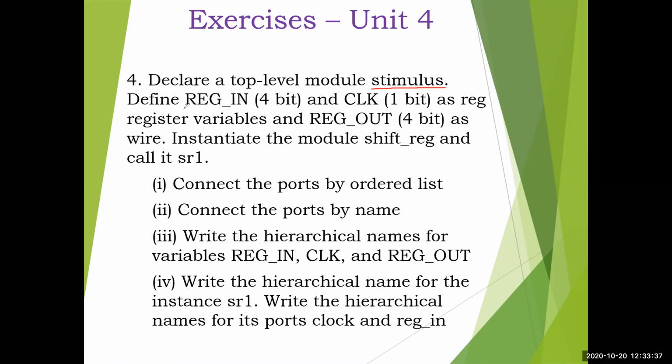In that, define register in 4 bit and clock 1 bit as register variables, and register out 4 bit as wire. Like this you have to declare. Instantiate the module shift register and call it sr1.